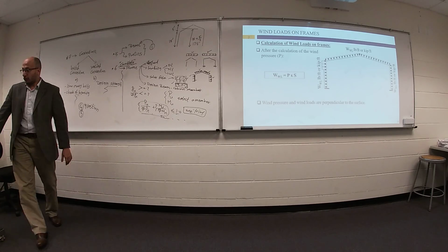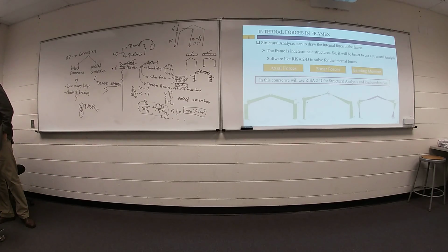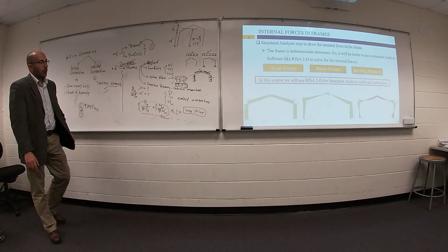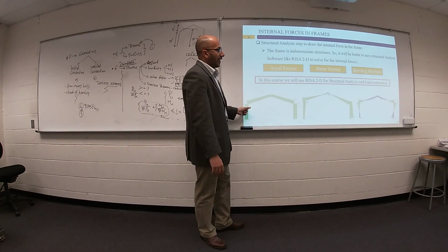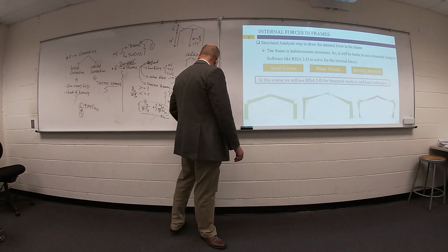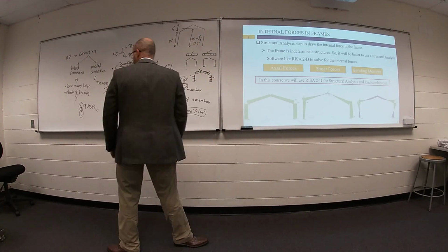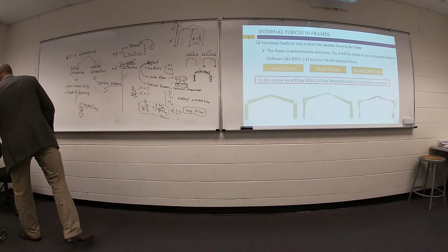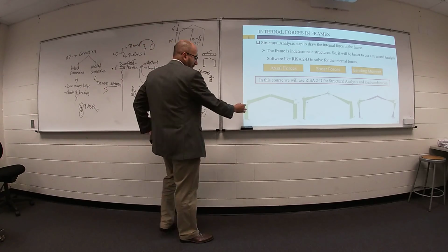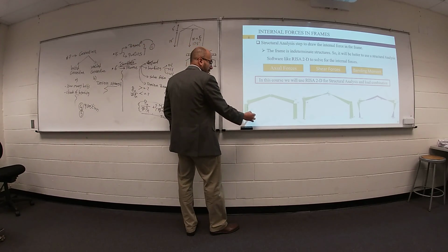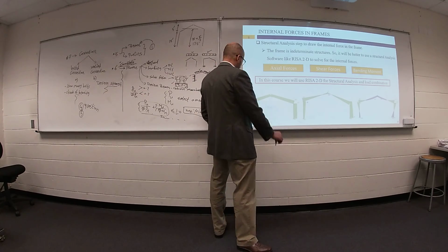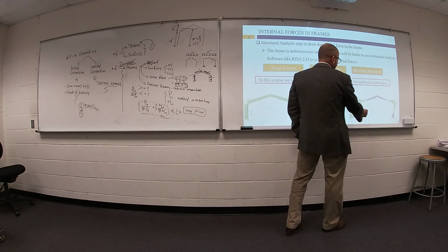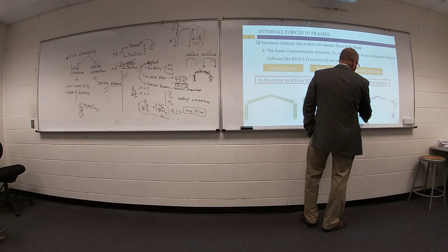Once you get your results, what is the normal force value, which is compression, which will be P ultimate. This maximum value here will be P ultimate from the normal force diagram. From the bending moment diagram, your maximum moment will be M ultimate.